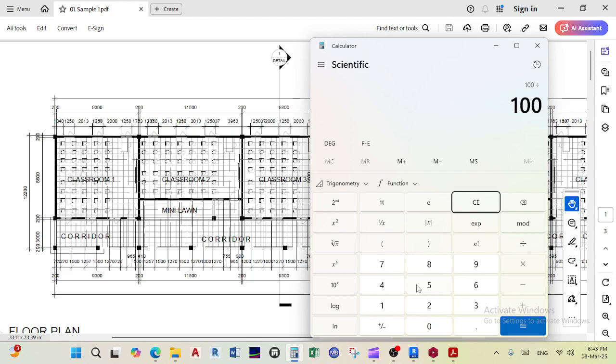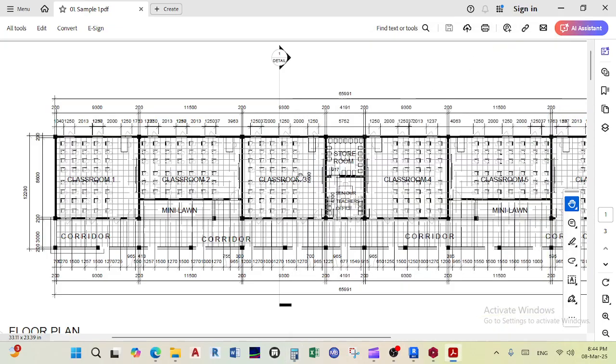If each truck will carry 10, so we're talking about 10 trucks. And if you're spending about 30 minutes or even an hour, 60 minutes on each, so we've got about 600 divided by 60 to give us 10 hours. So now imagine having to cast concrete for 10 hours.